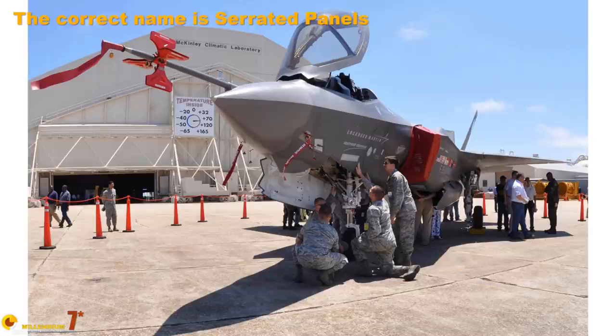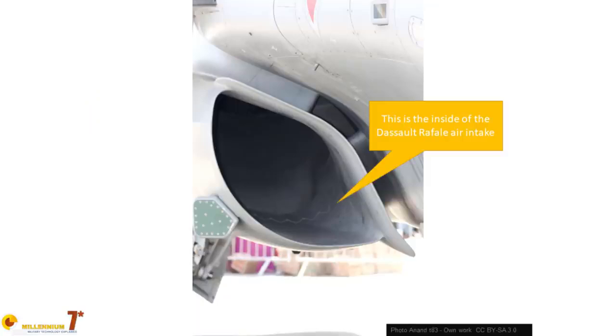Also, jagged panels do have specular reflection toward low priority directions. This is the reason why all stealth planes have this sawtooth appearance that is their typical look. And also notice that the sawtooth reduces the distance that the surface wave can travel, so the Keller cone intensity is reduced as well.